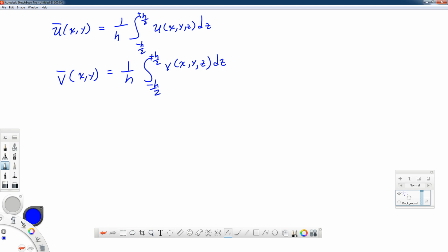This reduction down to two dimensions is often seen in finite elements. For two-dimensional finite elements, continuum-type plate elements, you'll use and define a middle surface value and a thickness, and then bending stresses and so forth are extrapolated out to the top and bottom surface away from that defined middle surface.